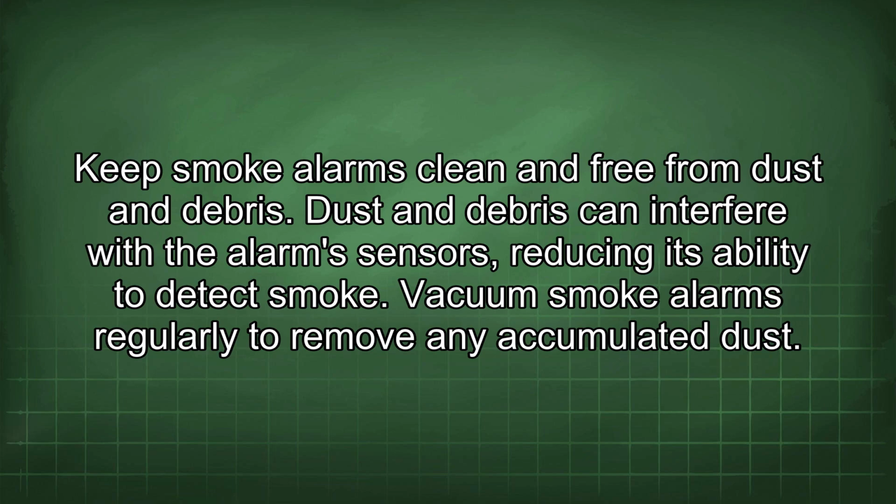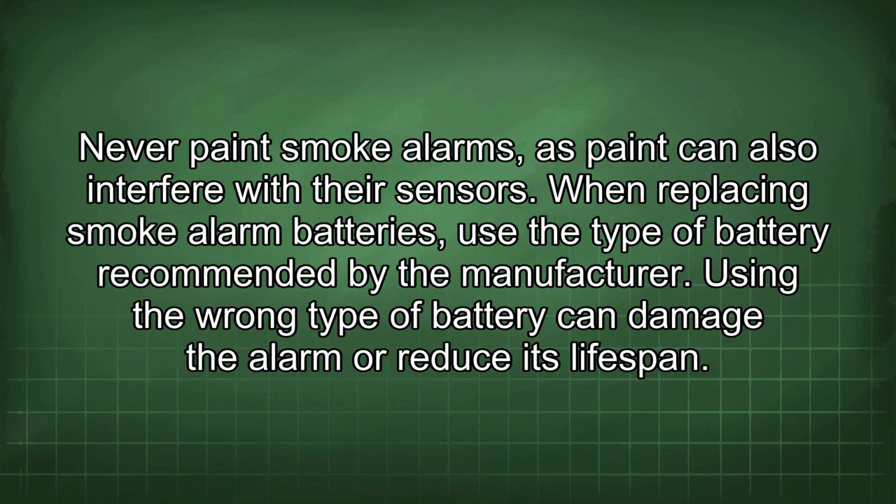Keep smoke alarms clean and free from dust and debris. Dust and debris can interfere with the alarm's sensors, reducing its ability to detect smoke. Vacuum smoke alarms regularly to remove any accumulated dust. Never paint smoke alarms, as paint can also interfere with their sensors.